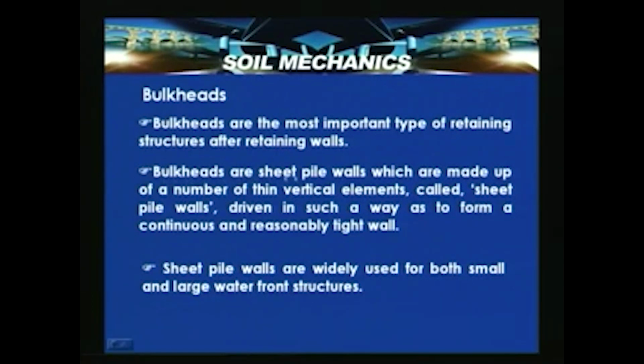So bulkheads are sheet pile walls made up of a number of thin vertical elements called sheet piles, driven in such a way as to form a continuous or reasonably tight wall. And sheet pile walls are widely used for both small and large waterfront structures. So these are also used, in some cases, as part of berthing structures in the marine environment also.